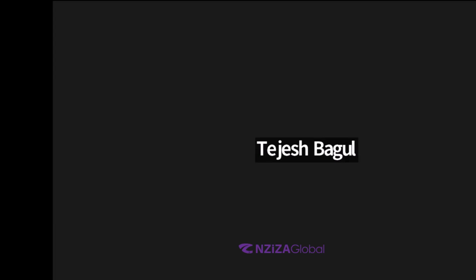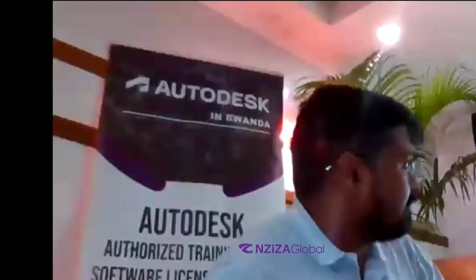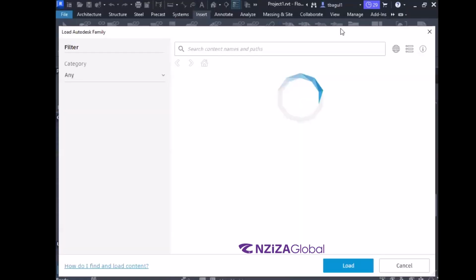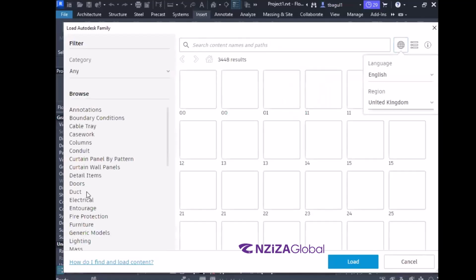Okay. So I'm going to repeat the process again. Insert ribbon, load Autodesk family. The reason we are doing this is we do not want a duplex receptacle. We want a simplex. That means there is just one receptacle, one outlet in that family. So we are going to insert ribbon, load Autodesk family. Over here, make sure you have the locale setting properly assigned to United States Imperial. And then click on the electrical.